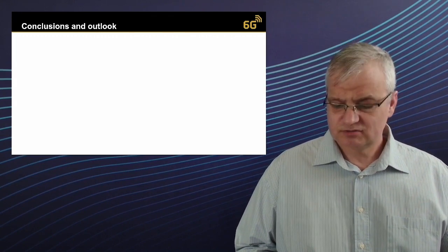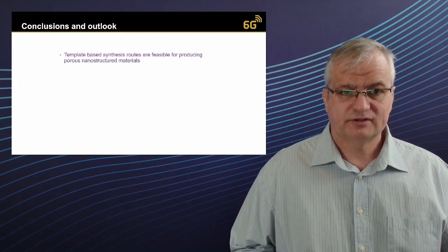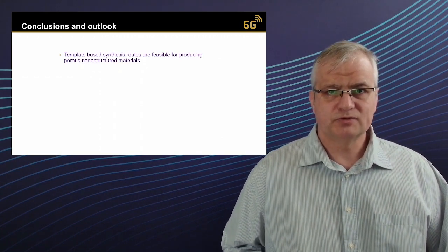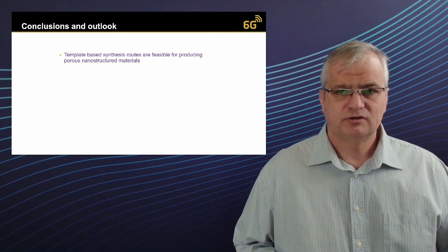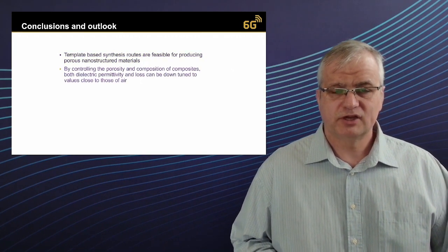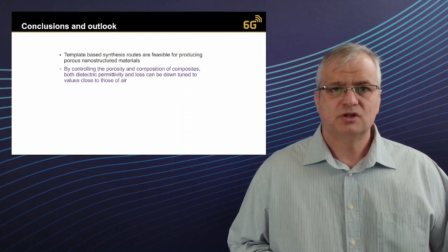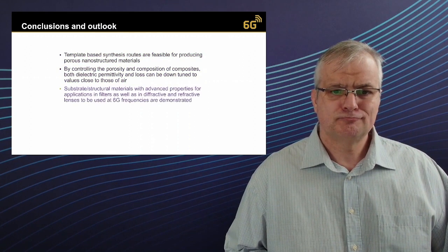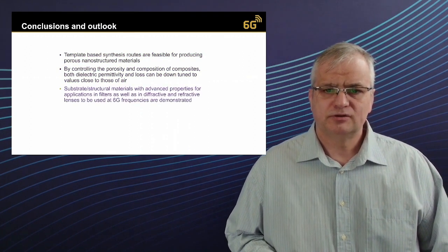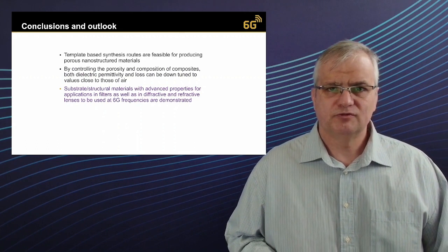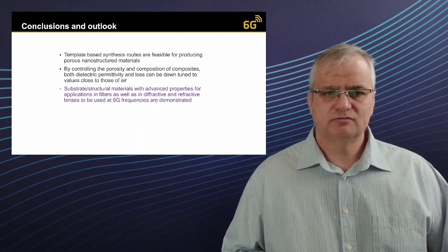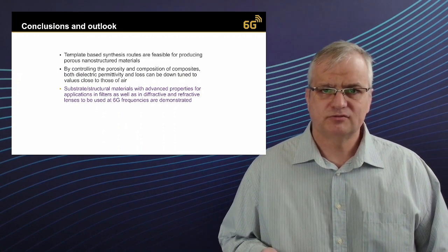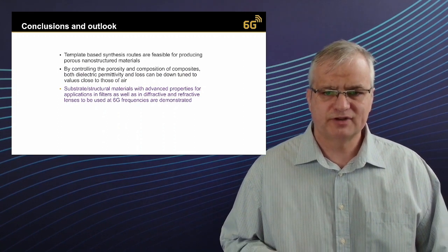So in conclusion, we have shown that template-based synthesis routes are feasible for producing porous materials that we can then apply in high-frequency devices having very low permittivity and electric losses. These devices were demonstrated in filters and lenses at 300 gigahertz frequencies.